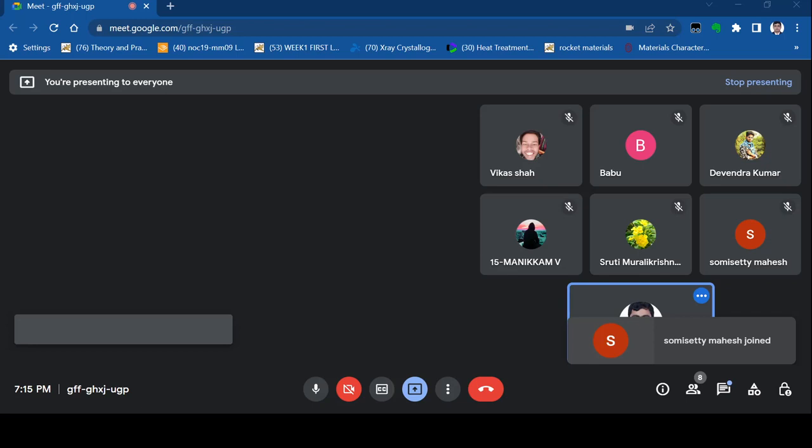Then minus delta H fusion. As I said, because we are going from liquid to solid, we have to reject the enthalpy of fusion, then only we can solidify. So this is a minus sign. Then again plus, from D to B, 1000 to 900, integral of Cp of solid dT, because this is the solid line. So is this clear? Everyone got it? Yes, sir.